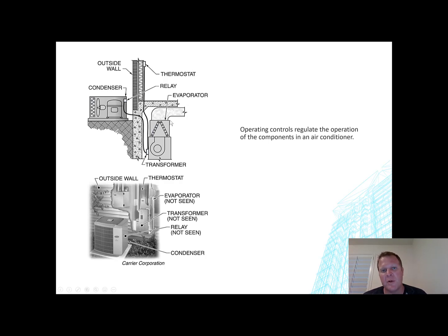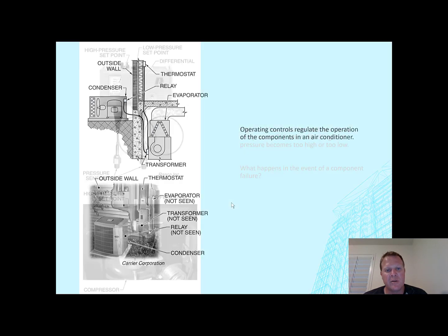And now you can see, I'm hoping that on the much larger project, it's the same basic principles. It's the thermostat. It's trying to control multiple pieces of equipment, and just how smart it is, how much equipment is involved, same kind of thing. It's really just something simple like: turn the fan on. Will you make this coil work? Will you work on the refrigeration? Will you open and close this damper? Hey, the thermostat says that it's fine. The pressure switch. It's not very complicated if you think about it from this perspective. Just little pieces you've gotten, and you should be able to apply them to the larger pieces.